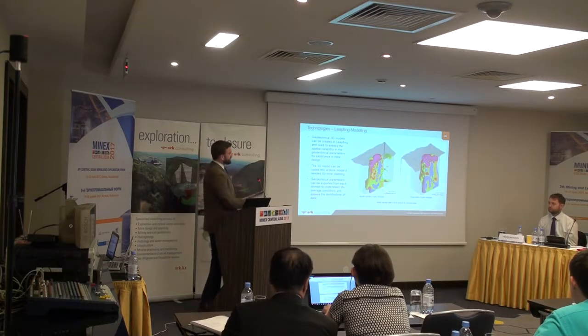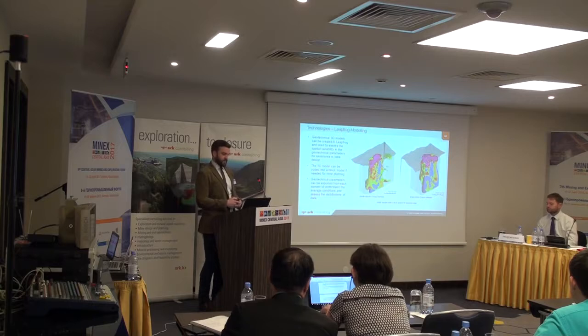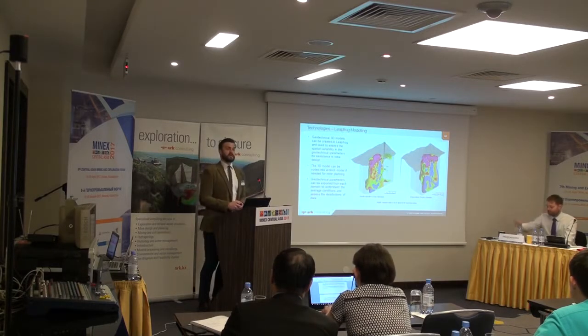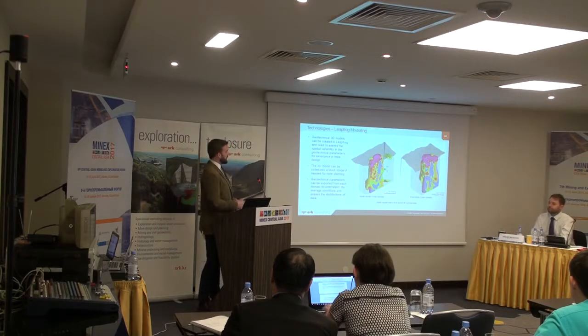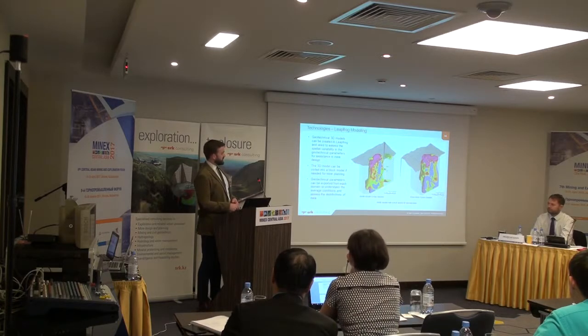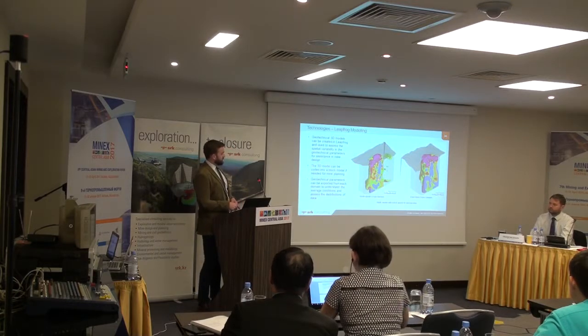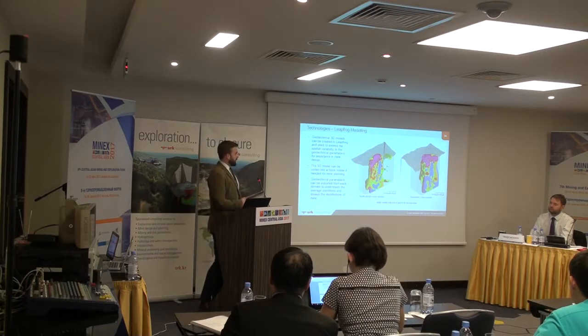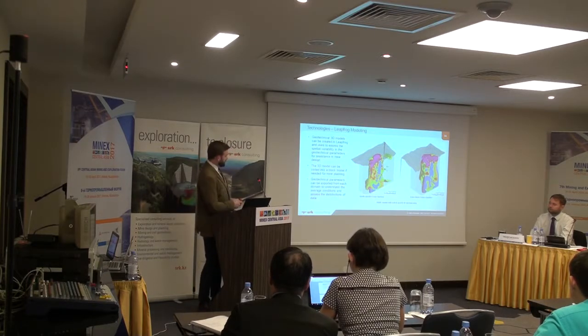I touched on leapfrog modelling earlier. There are applications in Leapfrog which will enable you to carry out 3D geotechnical wireframe modelling, and we're using these more and more on our projects. The 3D models can really show the variability in the engineering properties of the rock mass, and what I'm showing here is a 3D geotechnical model showing the variability in rock mass rating for a copper porphyry deposit.